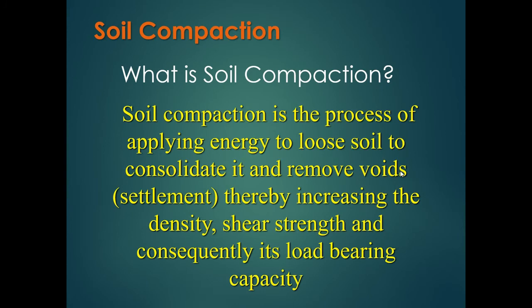Remember, compaction is the process of applying energy to loose soil to consolidate it and remove voids, therefore increasing the density, shear strength, and consequently its load-bearing capacity. This is why we need to compact soil.